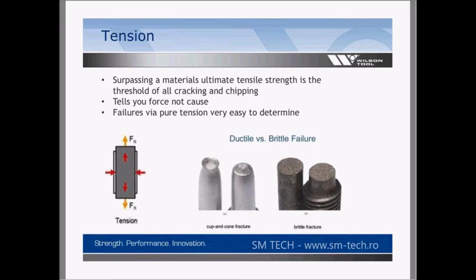Your M2s and your other powdered M4s and molybdenum-based materials see a little bit of that as well. But when you add more vanadium and get a higher Rockwell into that T15, 10B range, carbide obviously does that, and the benefit is it breaks. Your safety features will catch that. So depending on how your dies are designed, keep in mind you want to make sure your materials will follow that process as well.